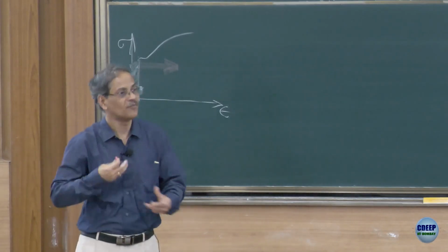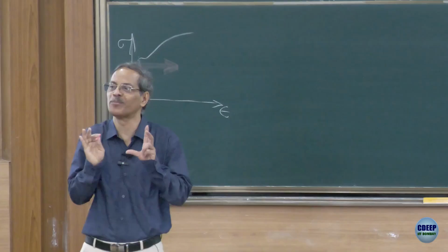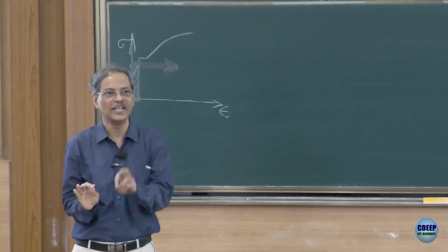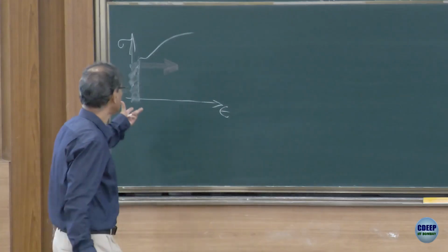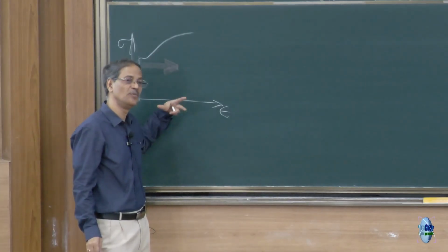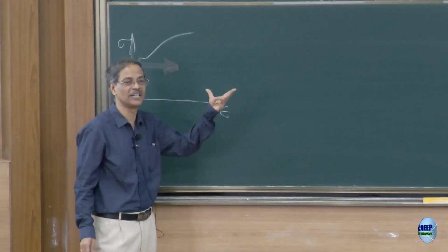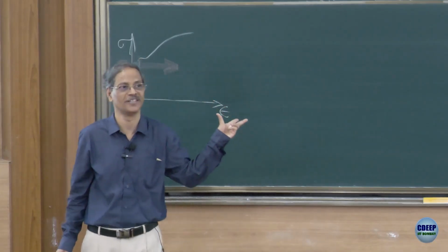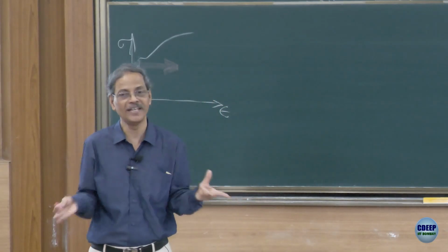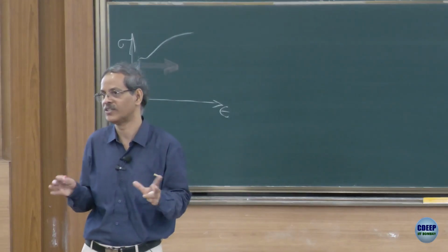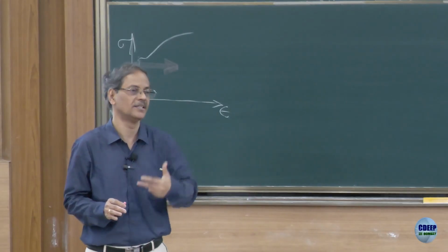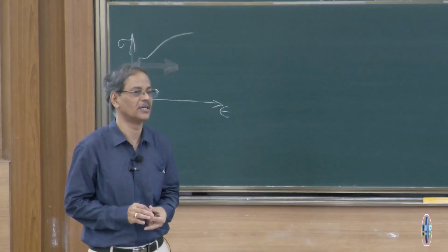Okay. So, you have to use the stress strain relations appropriate for your domain. I am simplifying the problem. It is inherently non-linear for manufacturing people, the stress to strain relationship. Strains will be large, even the strain displacement relations that we have taken will not hold good, because it is undergoing large deformations. So, do not blindly use whatever we are discussing in the class, because you have to go back to the roots and understand the governing equations, and accordingly you should use it.